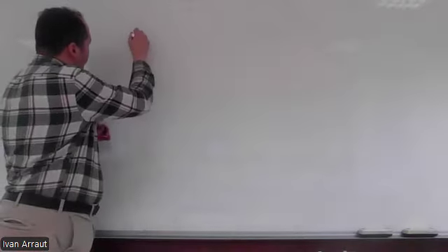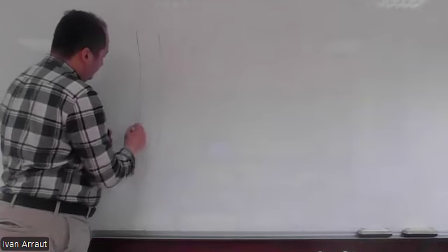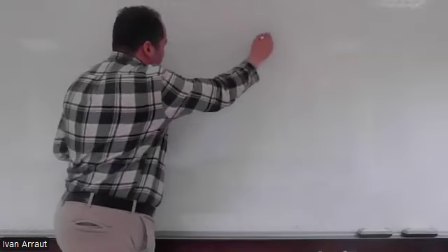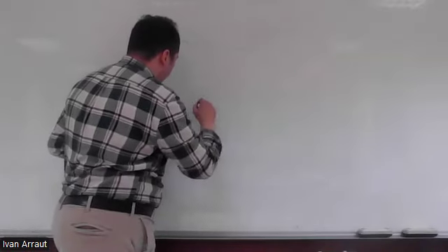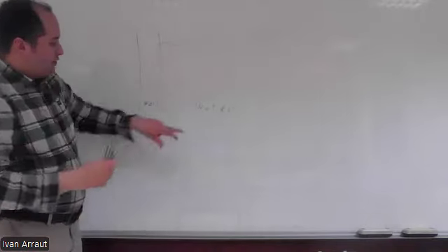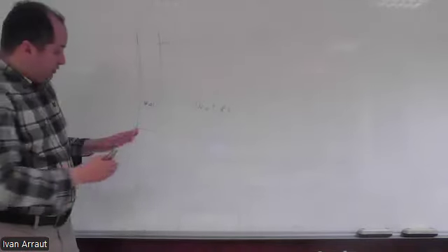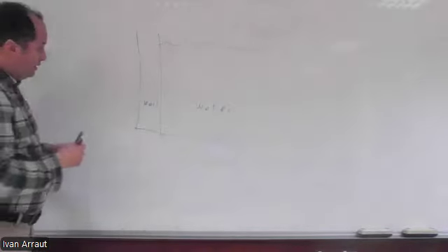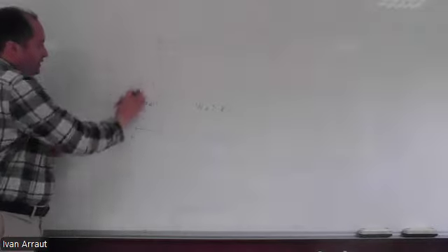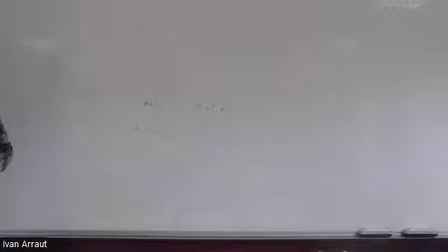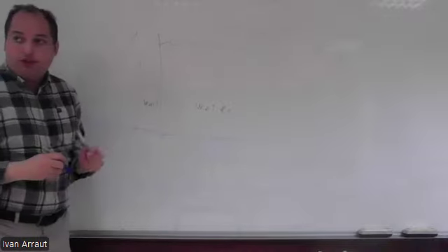If you make this wall and the water is contained here, this is water, you have to take into account that the pressure here is larger than here. So your wall has to be highly resistant at the bottom. That's why you will see these walls, in reality, designed like this. It's mostly like that, and the reason is the pressure here.